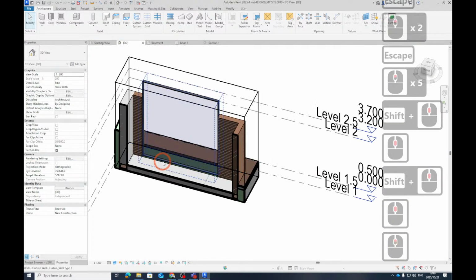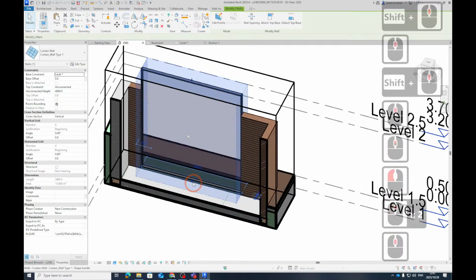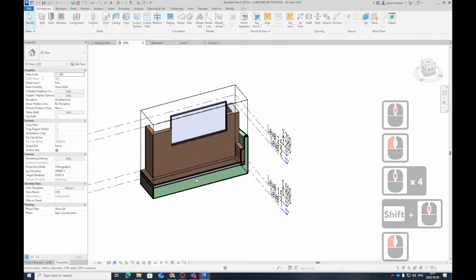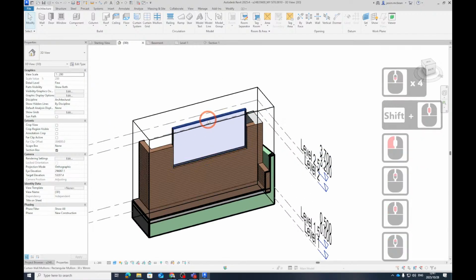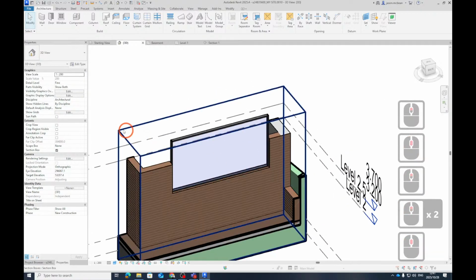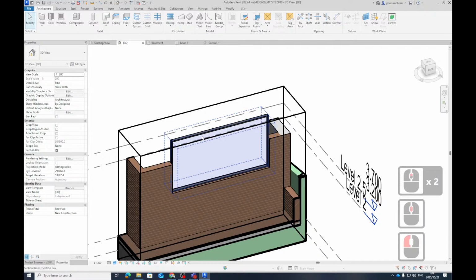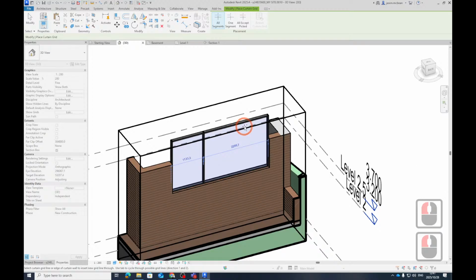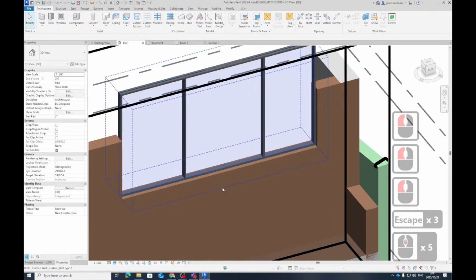Now, this internal curtain wall, if I start it over here, see what it does? It becomes like a window. So this is a quick way to add windows. Now, these systems, I'm going to duplicate. You can go and add grid mullions. So this is if you want to do it manually. So you're going to say curtain grids. Oh, so you can add them.